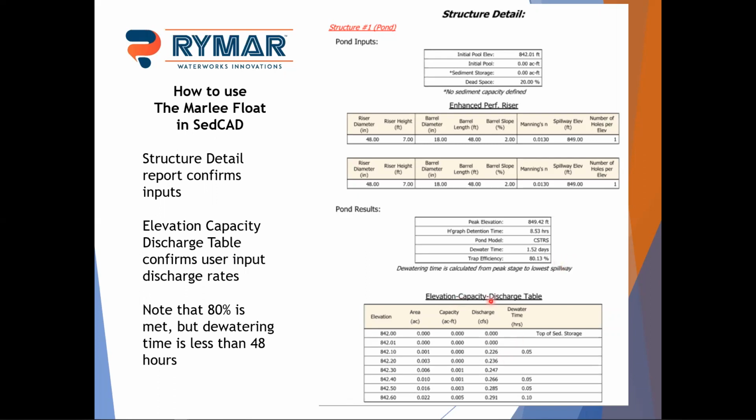And if you look at your elevation capacity discharge table, you'll see that the discharge matches what you plugged in for your user input for your skimmer. And as that table goes on up to 8 feet, it follows that till the top of the riser kicks in.